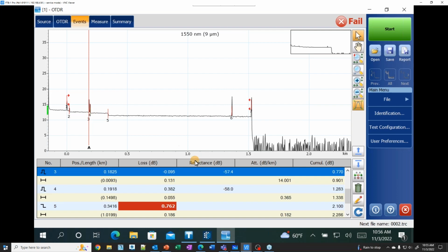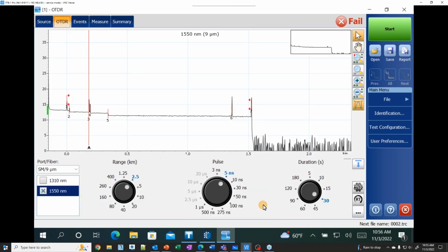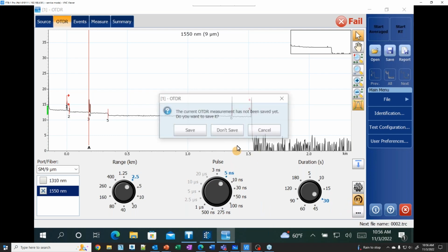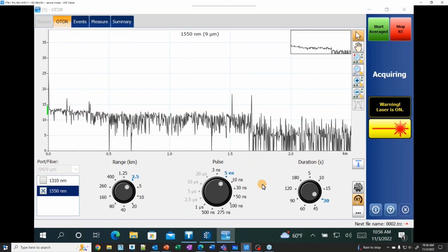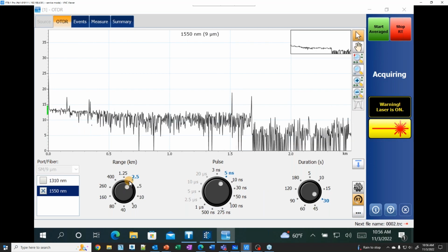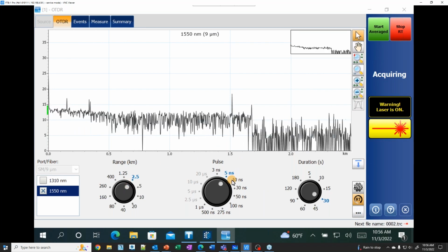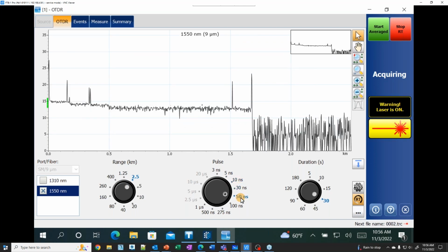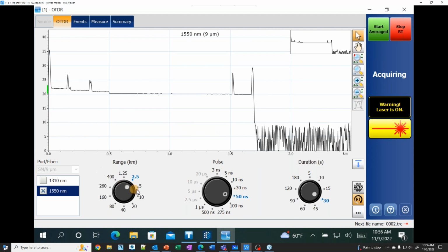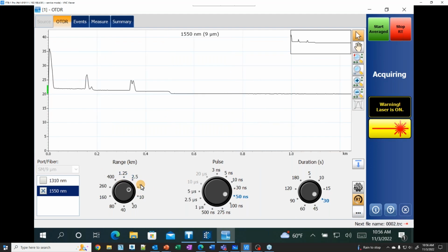And so this is basically how I set up an OTDR, and a lot of it is just really the interpretation. So in this day and age, how I do it is I will select a short range, a short pulse width, and I will shoot it in real time. So instead of using auto, if I'm testing with, like I say, a DWDM OTDR, I'll start with a short distance and a short pulse width so I don't overpower the receivers. Then I'll increase my pulse width until this flattens out. There it is. Then I'll adjust my duration, my distance to whatever it needs to be.